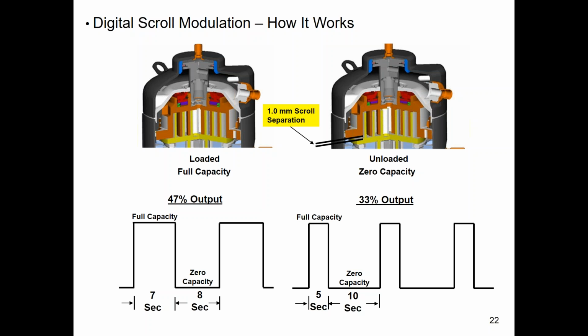Too many ifs. Yeah. So it sounds like if you're designing a project where you absolutely positively have to bury the lines, you probably should switch the job to a chilled water design and bury the water pipes and have a chiller feeding hydronic coils instead of having a DX system feeding refrigerant coils. Exactly.